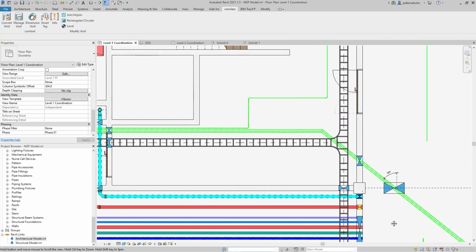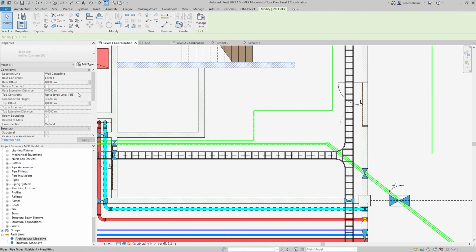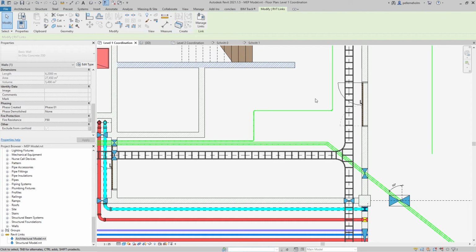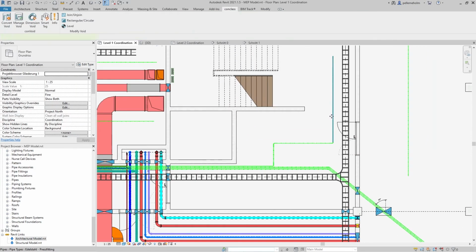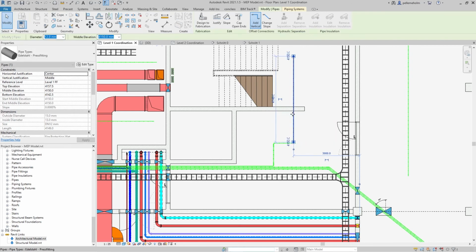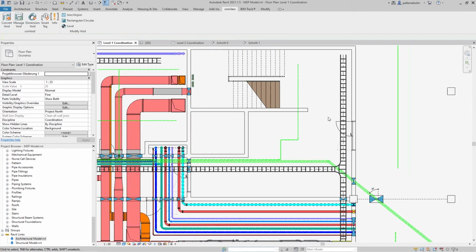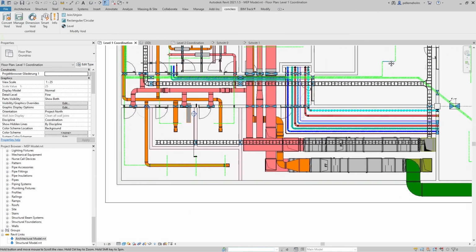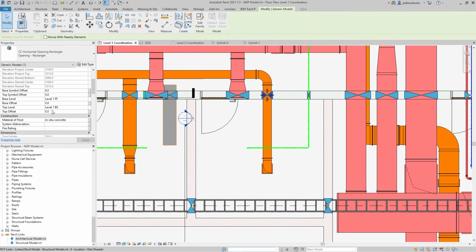This also applies to structural and architectural elements. In this case, the structural engineer excluded the wall from the process to avoid that the MEP engineer is placing openings there. If an MEP element intersects the wall, conVoid will recognize the excluded wall and not create an opening. I can also exclude the openings in case I want no changes made by conVoid.